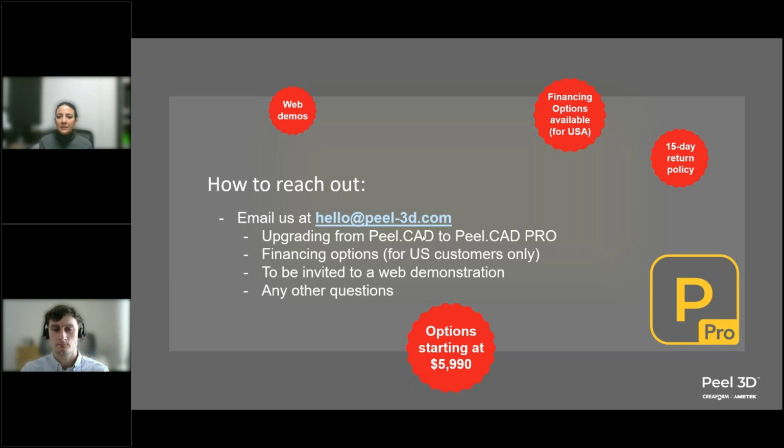Or I know that some software also requires you to decimate before sending the STL in. So that might have been my own experience, and I didn't know that at the time. But if you do decimate, I know Fusion, for example, likes it when you can use like 10,000 triangles instead of whatever million triangles you might have. And so we have a tool called Decimate that allows you to lower the triangle count. So I think that one's also maybe a case by case basis, but if you could also reach out to me, we can figure out what was happening there.